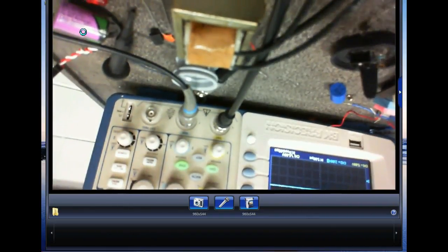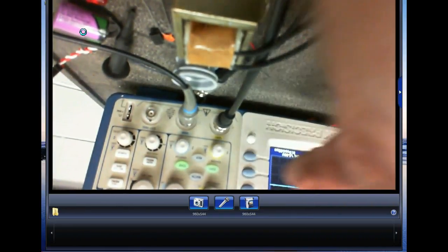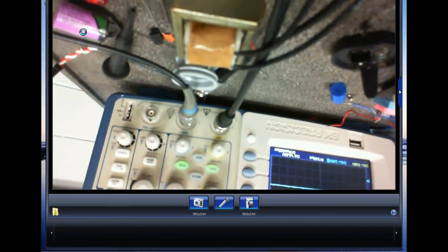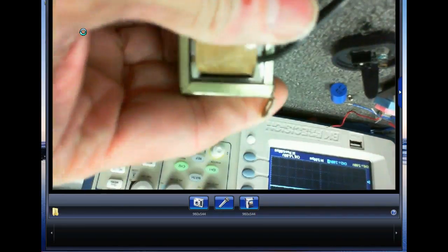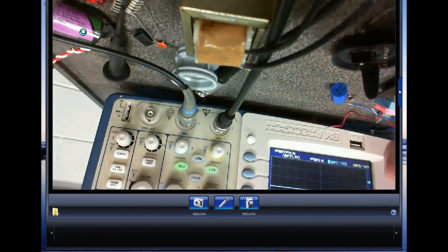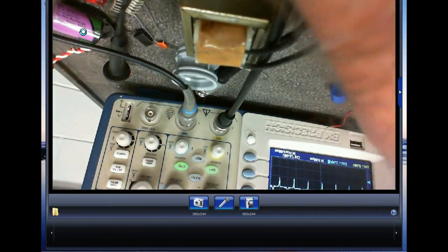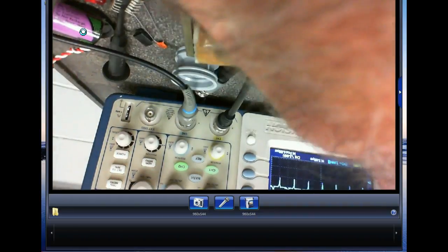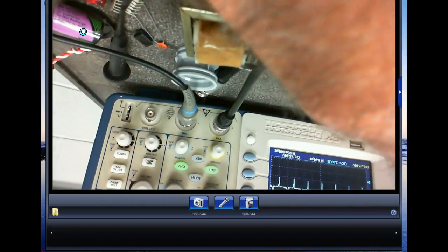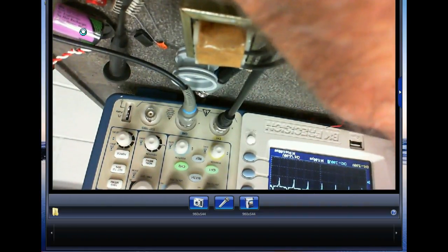So this is on this side. This scope probe is right here. This is the inductor. Here's my filter, and then this is on the output. And you can see the switching noise. So that's with the filter out, so you get that switching noise on the output. But it doesn't take hardly anything at all to clean it up.